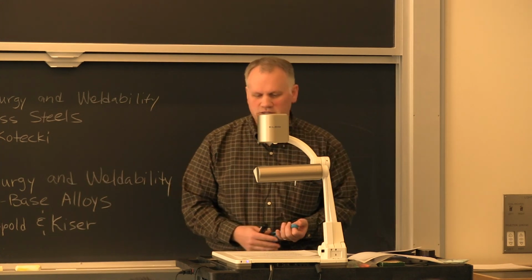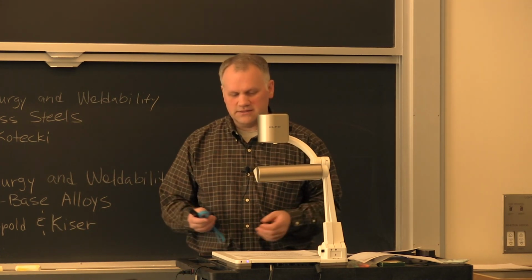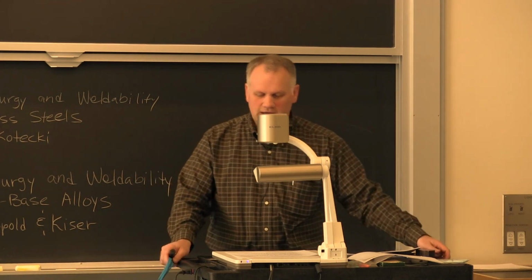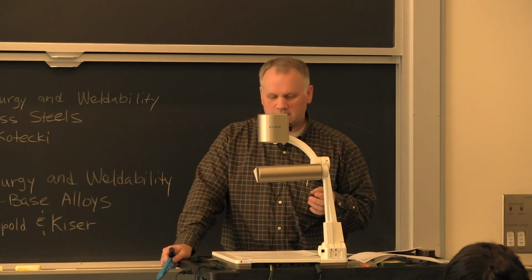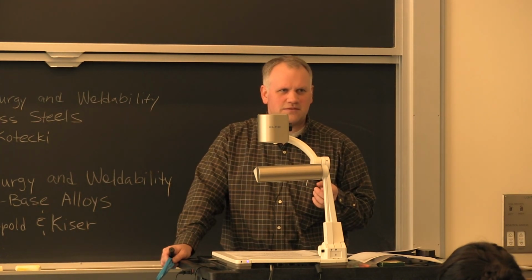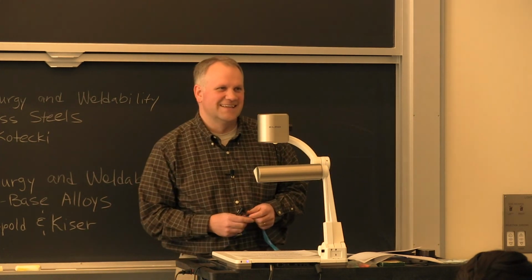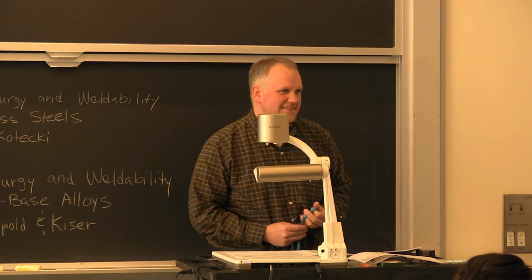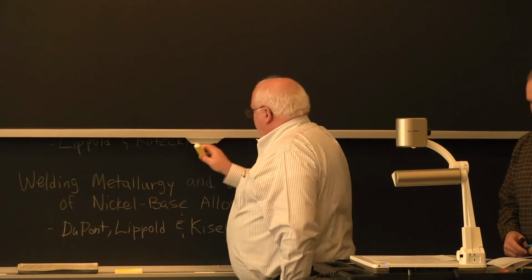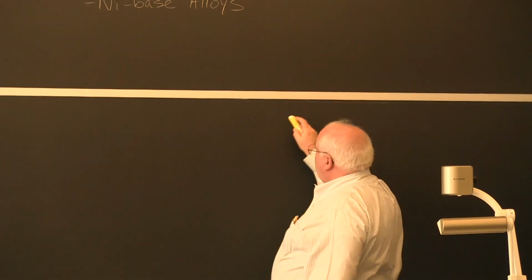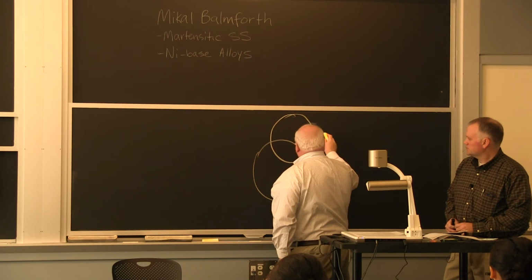Okay. Stress corrosion cracking is a form of cracking that can happen mainly in stainless steels, where you've got an environment that is corrosive. You've got a stress, and what's the third thing? A susceptible microstructure. Actually, we did sort of talk about it yesterday. Yesterday I drew a Venn diagram for hydrogen. That was stress corrosion cracking, yes.